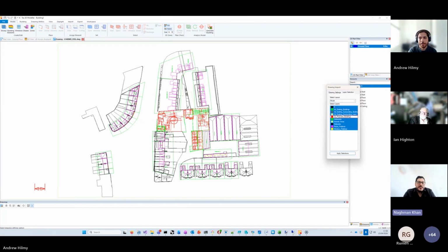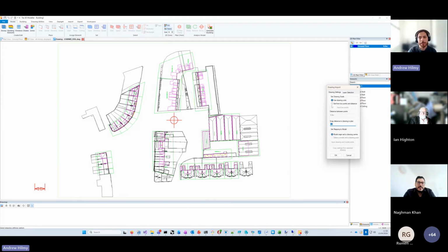Andrew, on the CBDM tool, can you change the hours for simulation? Like, if you want to set it to school hours, you can? Yeah, exactly. There's a little drop down. You change it from priority schools to other, and then you can choose the start hour, end hour and time step, for example.